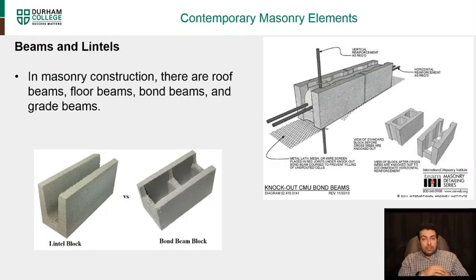Beams and lintels. This is something that we're going to go into a lot more detail on in masonry construction. There are roof beams, floor beams, bond beams, and grade beams. Just to show you an example, this is a lintel block. It is a solid block which is hollow from the top, but there are no hollow sections in the middle. That's why it's a lintel.